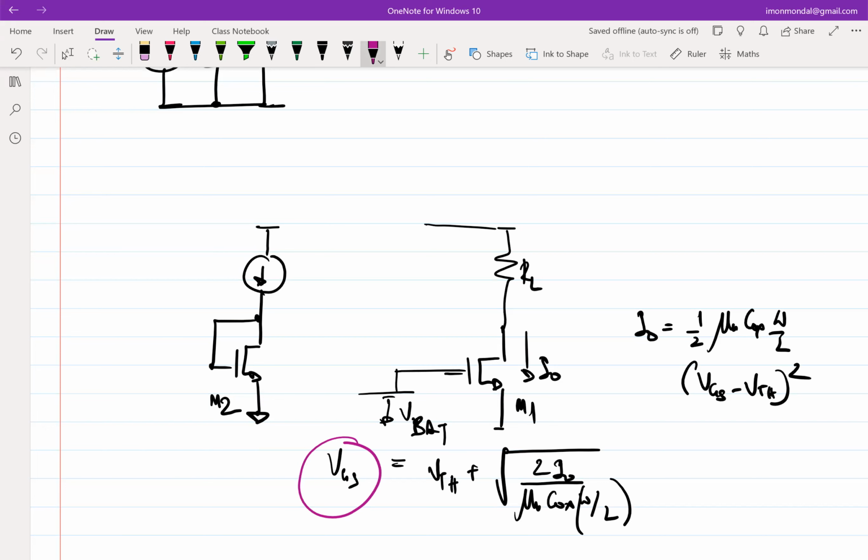But in this case, it is not. So what is the fix? Let's say I have another identical transistor M2. Does the VGS of M2 change with threshold voltage or is it fixed? It changes, right? So looks like the VGS of M2 has all the good things that we want, but VBAT doesn't have. So what is the solution?